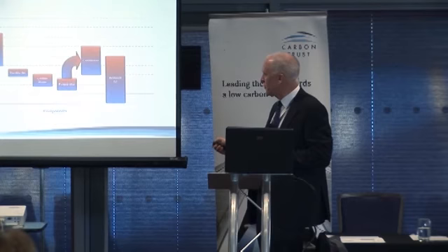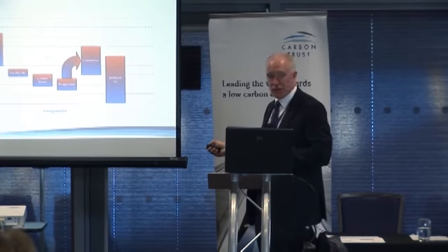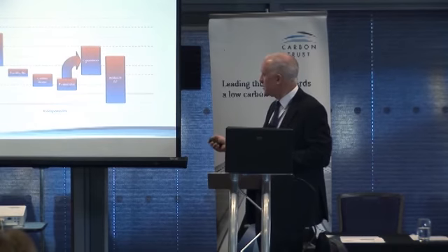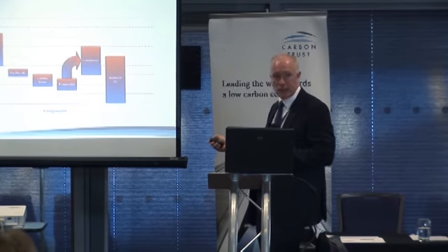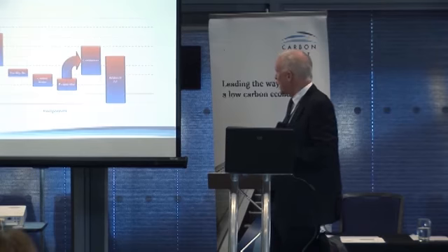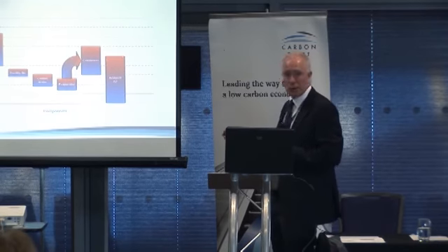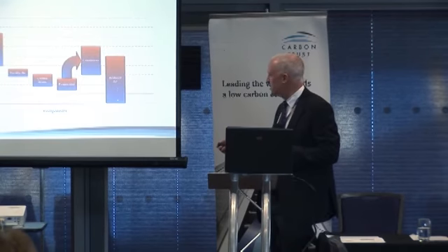That's generated often through a refrigeration system, with the evaporator providing the chilling at a lower temperature than that, and the condenser rejecting the heat out to the environment. And our ambient air is sitting here between, depending on the environment you're in, anything from hottest at 40 degrees centigrade right down to about -10.